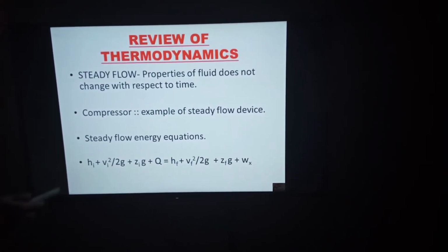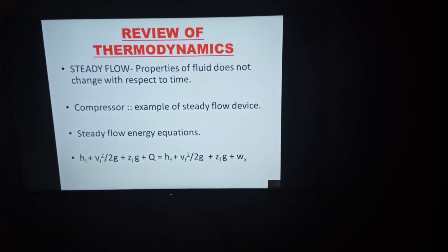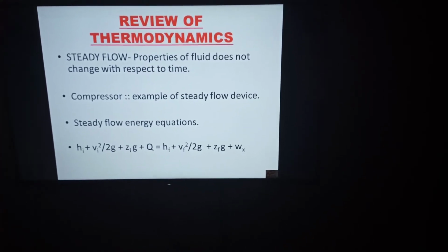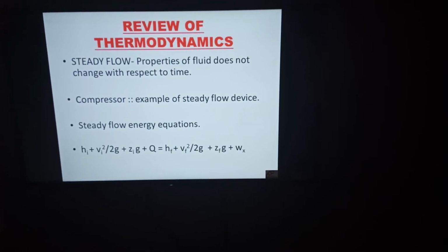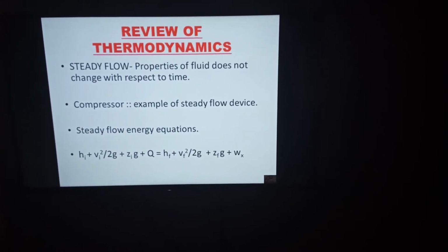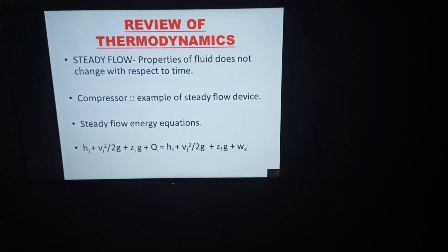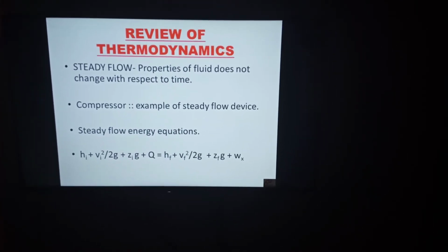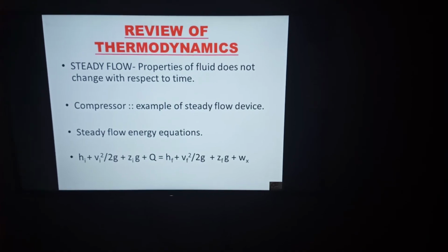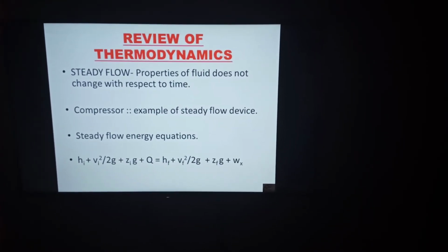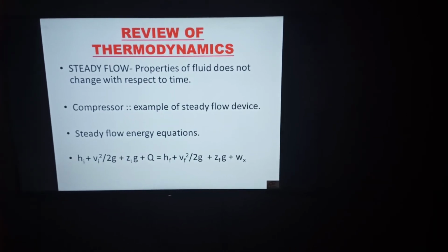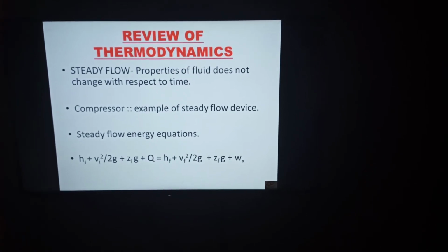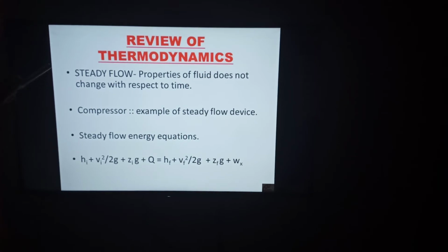Why do we need the steady flow energy equation? The main reason is that it is the basic energy equation for a compressible fluid, because here we are studying an air compressor and air is a compressible fluid. If it were water, then we would go for Bernoulli's equation, because Bernoulli's equation is the basic energy equation for an incompressible fluid. Since we are dealing with an air compressor, we have to consider the equation for a compressible fluid, that is the steady flow energy equation.